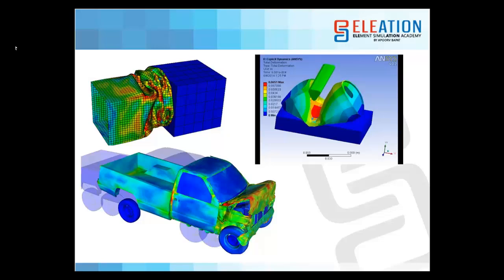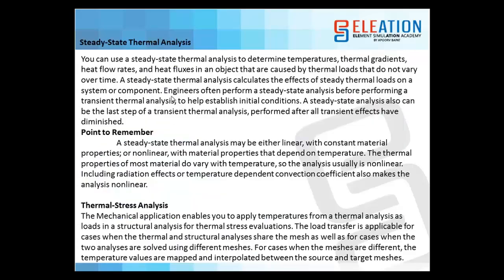So you can see here, for this particular time, this is the deformation which is coming. So we can see the actual phenomena, how the impact happened, what will happen at the time of impact, after the impact, the bounce back effect. All these things can be captured using dynamic analysis, which you cannot do in static. Static is for a particular instance, but dynamic is for the complete duration of the impact happening to your structure.